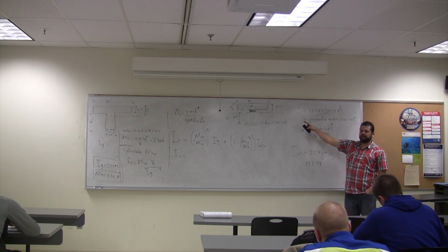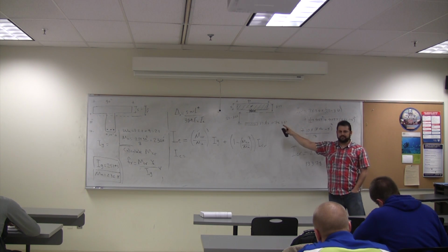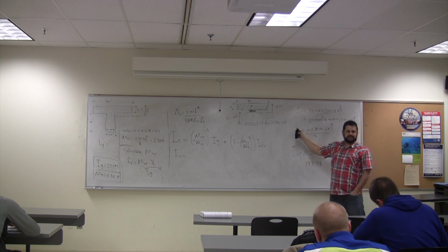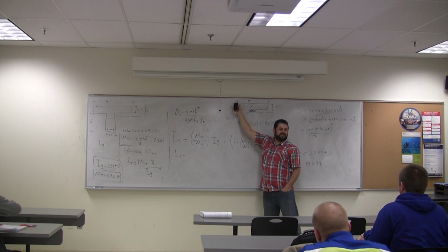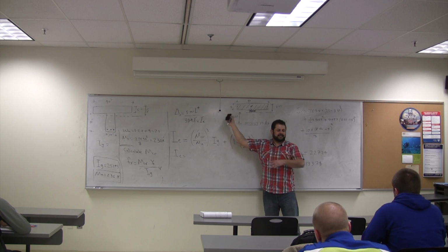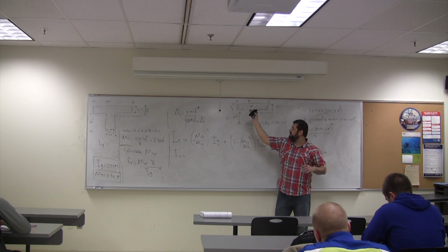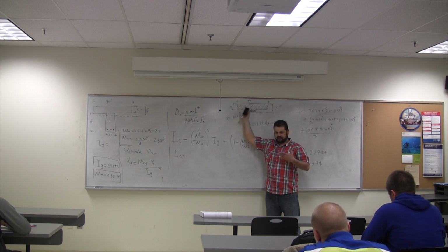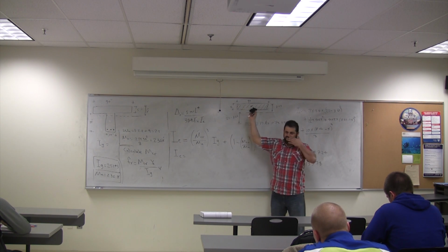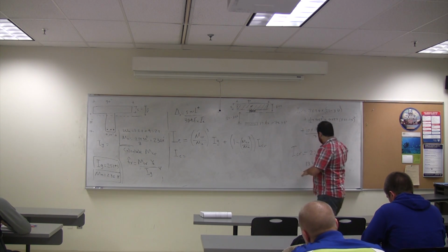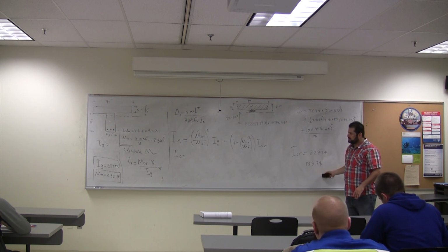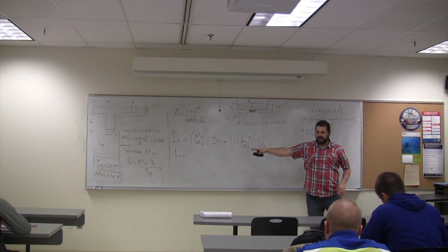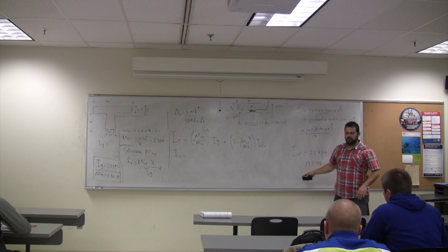This might not be accurate a lot. You know why? Because when KD is greater than the flange, this KD cannot be applied to this one. So what I said, we're going to assume the neutral axis at the bottom of the flange and calculate that. That's what I said the other day. And that's a reasonable number. If you do this one divided by that, the crack would be half what we have.